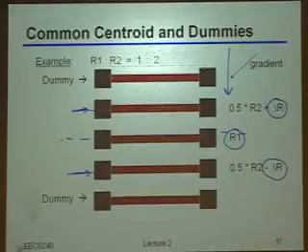Because as an example in this case, let's just pretend that for whatever reason the resistor was a little bit narrower on this upper piece. Well, if the gradient really is linear, then because I've placed everything symmetrically around the middle point of the whole array, however much this one is thinner, this one would be thicker by the exact same amount, or wider by the same amount, and the variations there would cancel. Okay? Does this make sense to everybody?